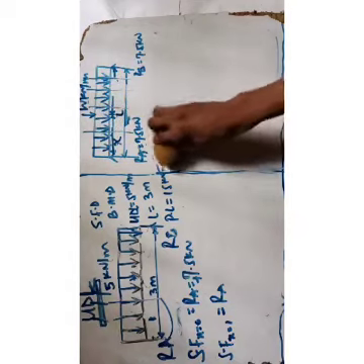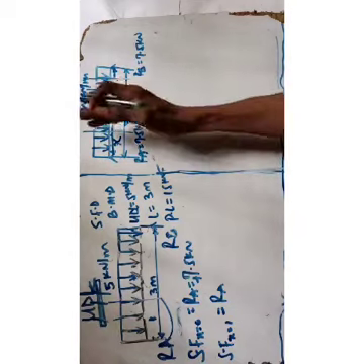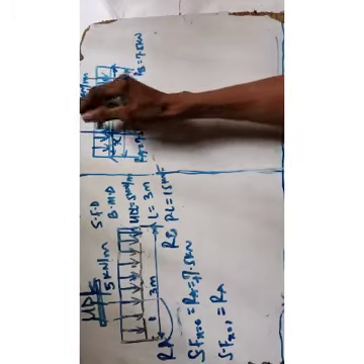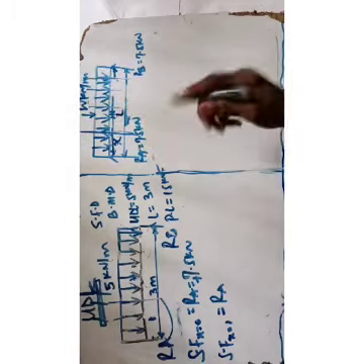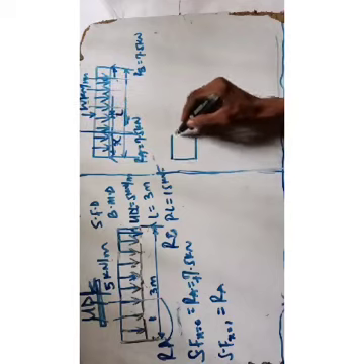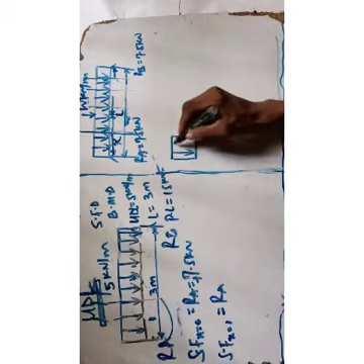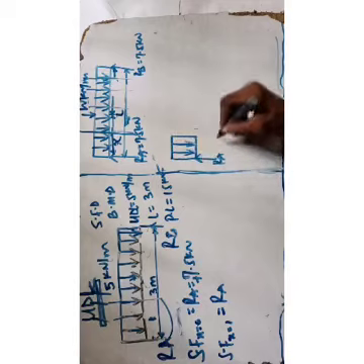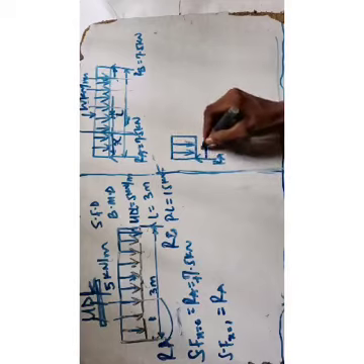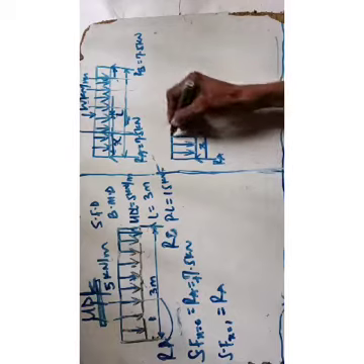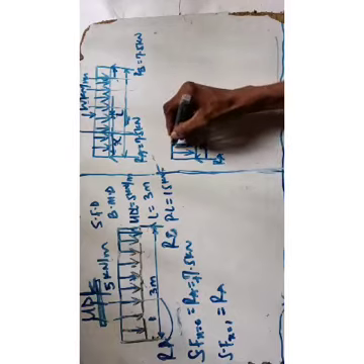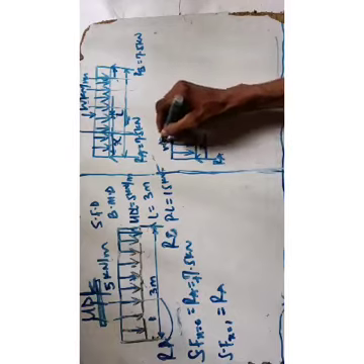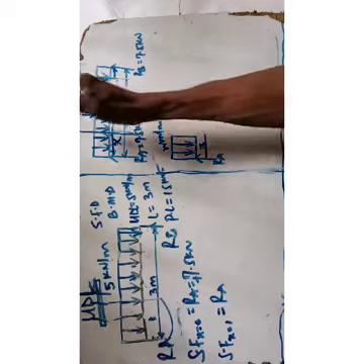Okay, so now if you want to find the shear force for this particular point, I want to bring this point out. It will be like this. So you have your UDL there, then you have RA. Now this point distance is what? X. Then you have the UDL acting on it, right? So the UDL there, we have the weight W kilonewton per meter. That is only for this point.